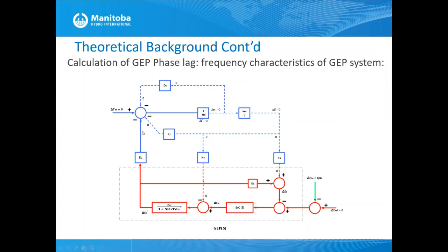Now, if there are any contributions coming from these, then we can't identify the input-output relationship between the input here and the output here. To negate any contribution coming from these, we increase the machine inertia to a large value, let's say 1,000 per unit. So any torque component coming here can't change the speed, because of the very large mass.